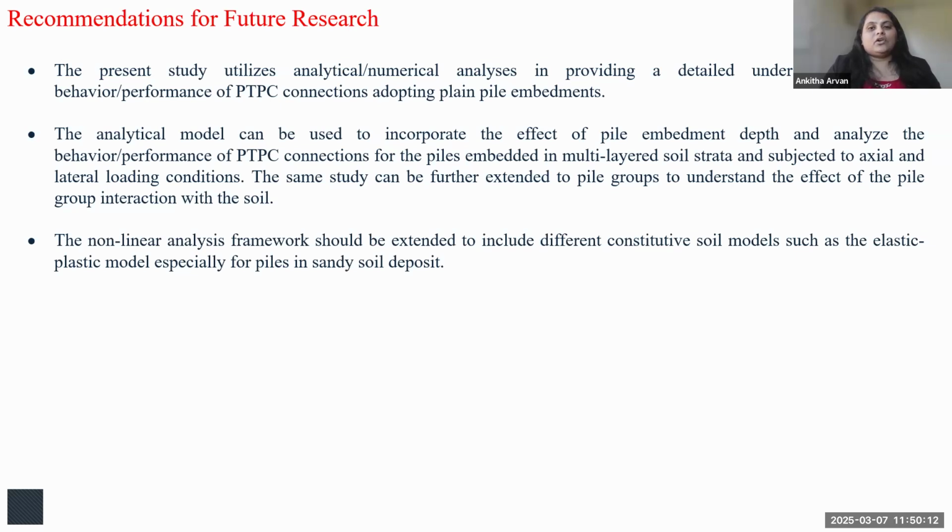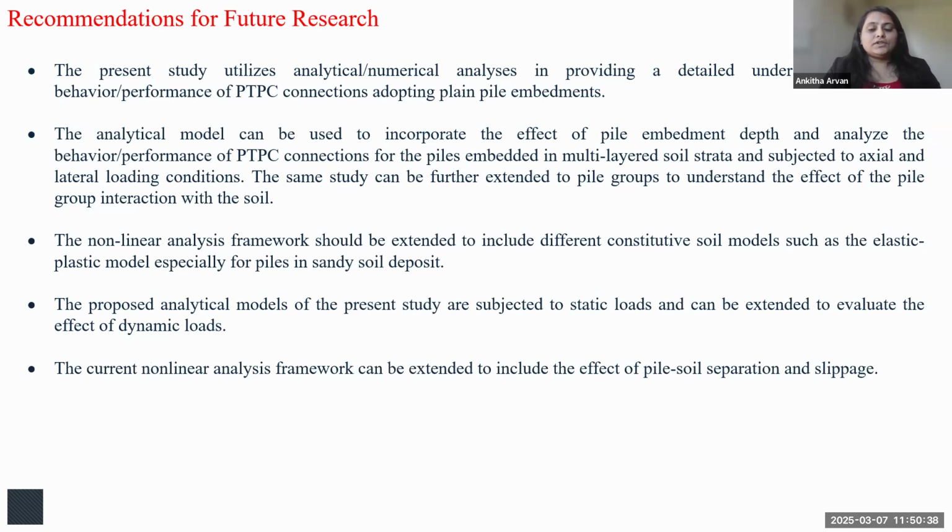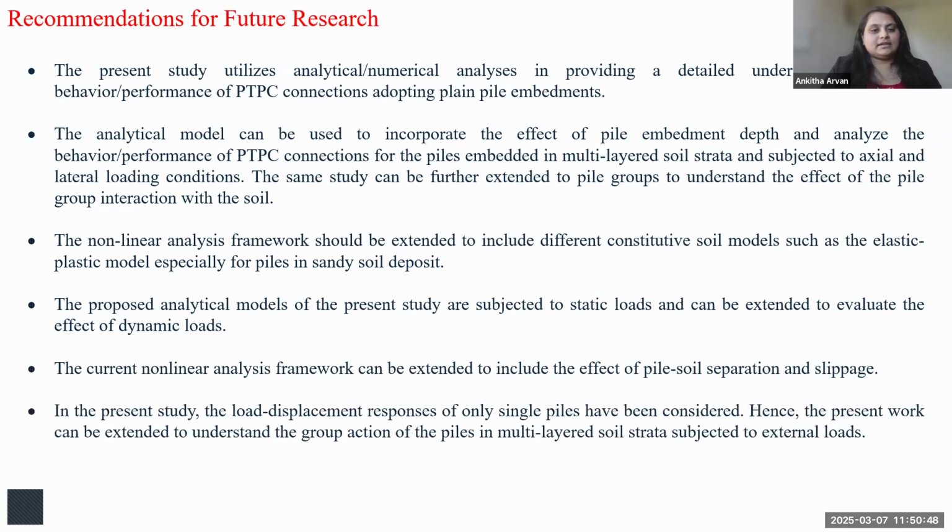And the nonlinear framework, like I said, should also have different constitutive soil models, such as the elastoplastic, especially in sandy soil deposits or some other types of soils, because right now I did work only for the clayey soils. Then the proposed analytical models are subjected to static loads and can be extended to dynamic loads, to understand the seismic responses. Also, this could include the pile soil separation or slippage, which is very difficult to trace, but developing a code could really help understand.